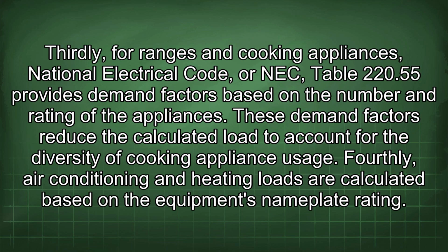Thirdly, for ranges and cooking appliances, National Electrical Code, or NEC, Table 220.55 provides demand factors based on the number and rating of the appliances. These demand factors reduce the calculated load to account for the diversity of cooking appliance usage.